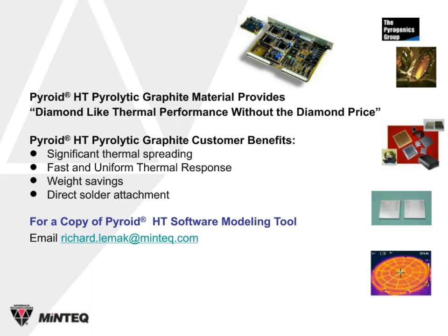James wants to know, can you create a surface by replicating a mandrel to match it? That's an interesting question, and the answer is yes. In fact, there's another way in which you can produce not the highly oriented pyrolytic graphite, but a more standard pyrolytic graphite can be made to net shape by exactly the technique that James is suggesting, which is by using the mandrel in a male-female type relationship. We do this quite regularly.